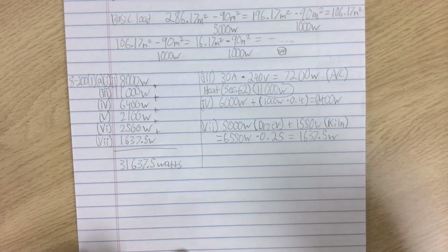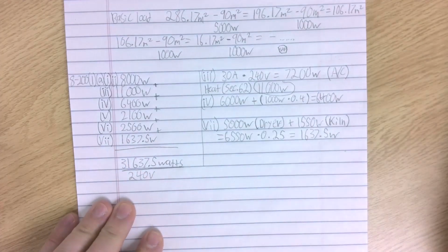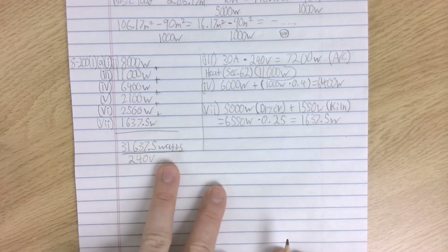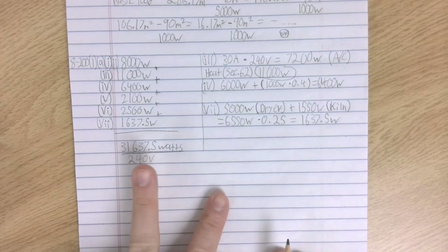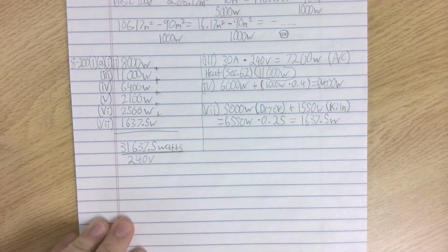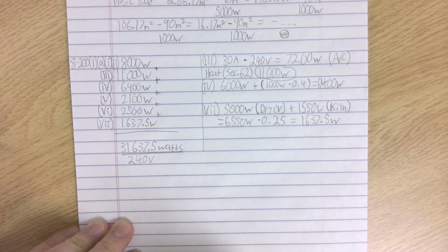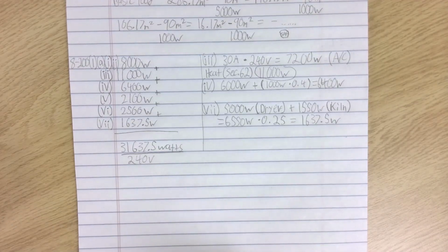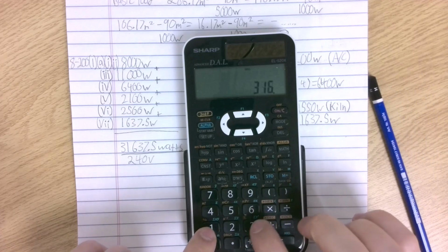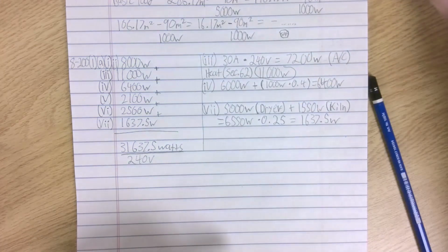We're going to talk about sizing overcurrents here. But first, I'm going to divide this wattage by 240 volts because it told me that's what my service was. And those watts are going to be across both phases or both lines, both hot wires, both live wires, both ungrounded wires. That's all the words I can think of for those wires. So I use my 240 volt divisor. That's my nominal system voltage. It's a 120/240 volt system. So 31,637.5 divided by 240 gives me 131.82 amps.